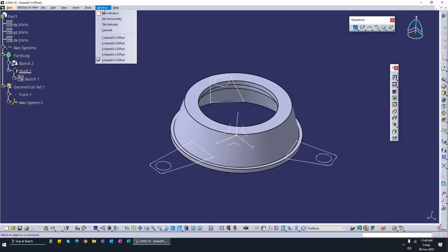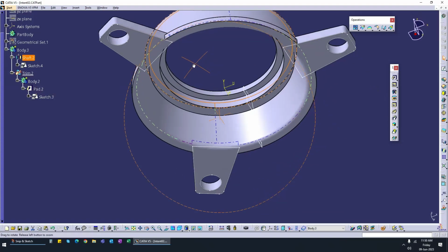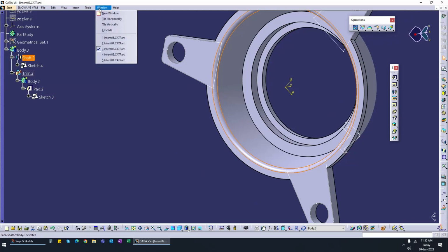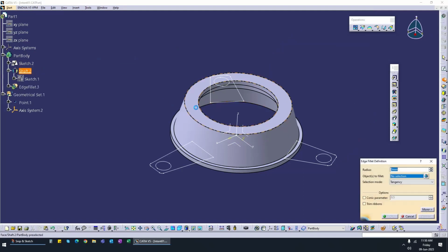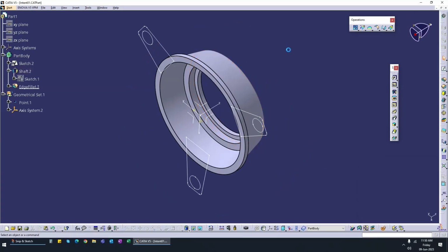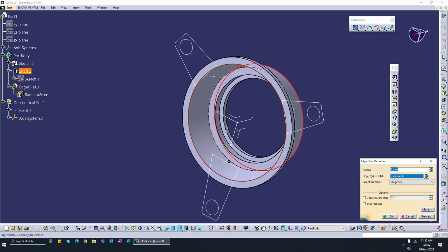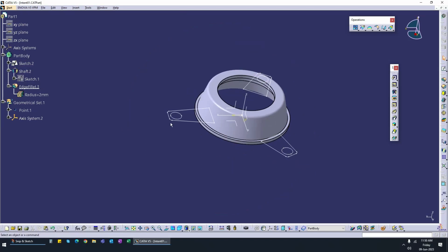Comparing to the other profile that we saw earlier, it has a smooth edge here, and it also has a smooth edge here. So to achieve that, what we can do is we can provide fillets on this shaft, 2 millimeters. We can provide it to the two edges within the same command. So we got our first part done.